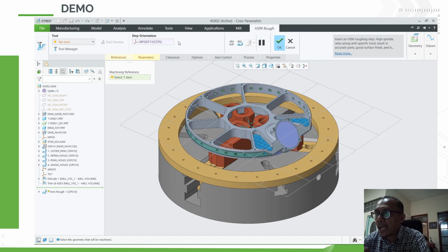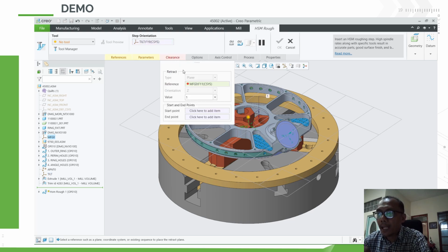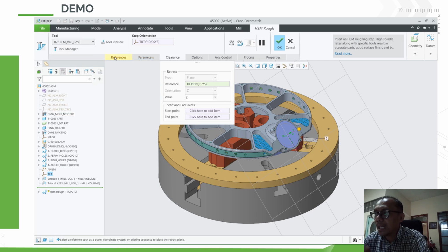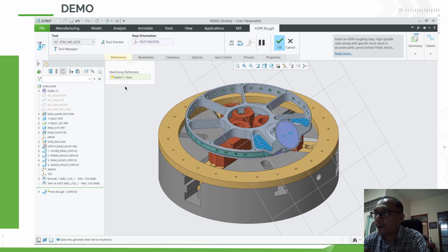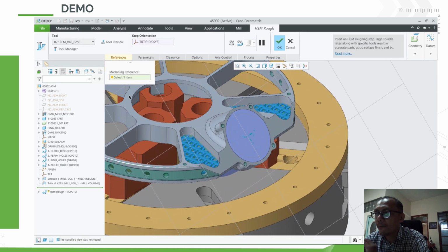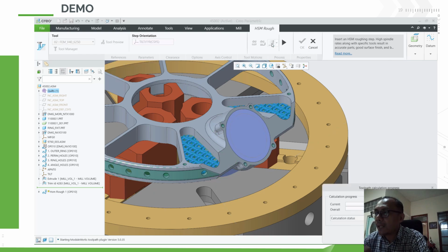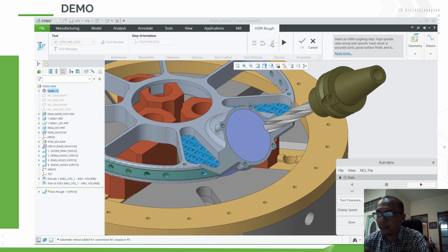Go ahead and play that toolpath, and now I have a roughing sequence that uses that mill volume, but it's high-speed milling. So that's good for all the roughing and rest roughing within the high-speed machining package. That's available to use with mill volume as of Creo 10.